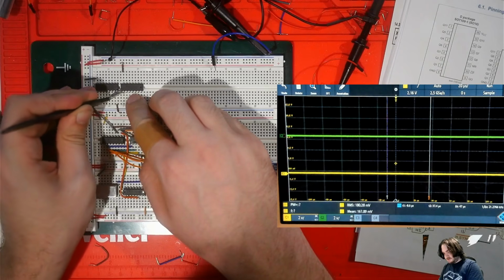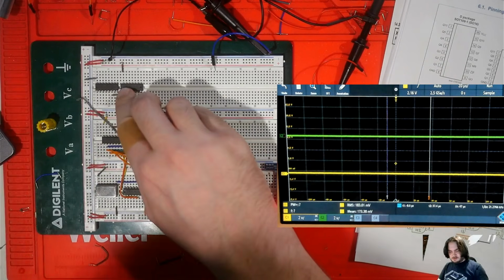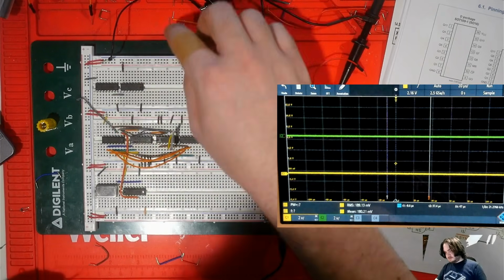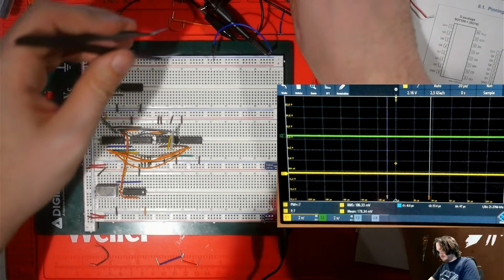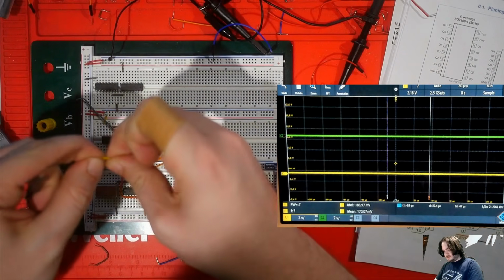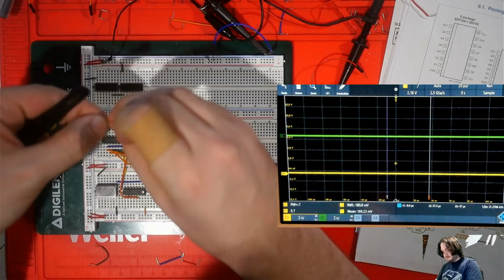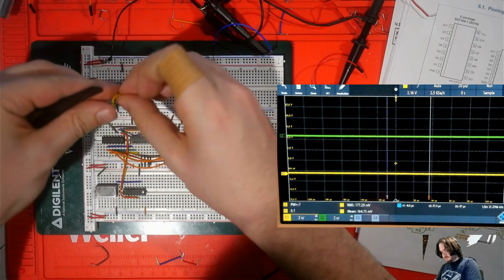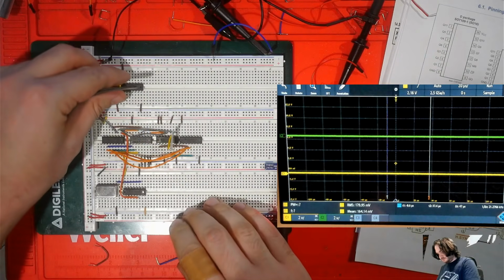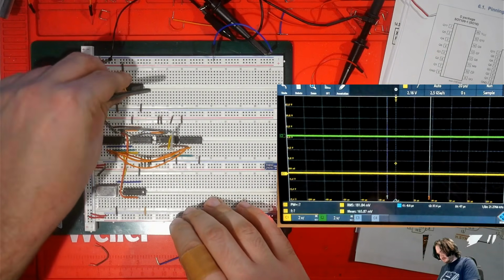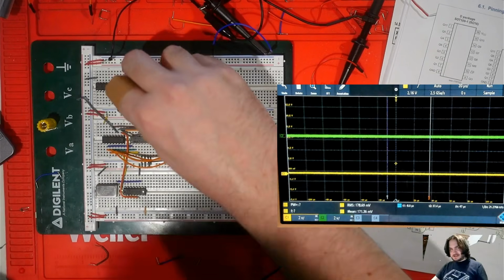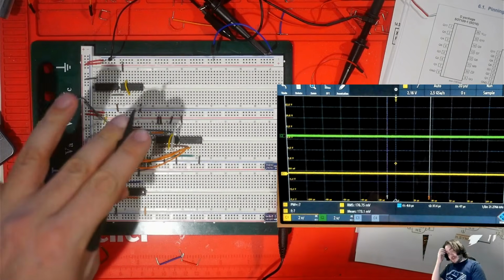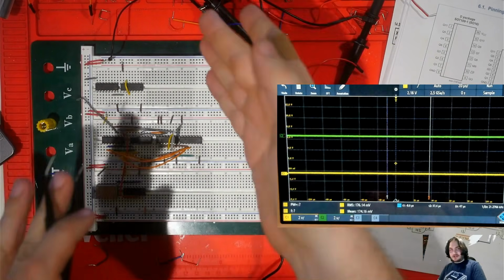That's the one. I'm going to bridge this to this side back here. The idea is we can NAND together two of these values, invert that to get regular AND, and then NAND that with the last value.